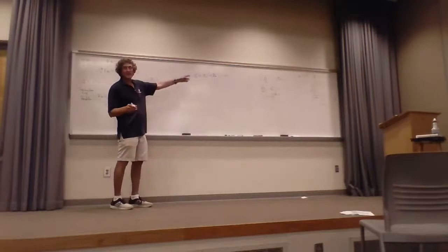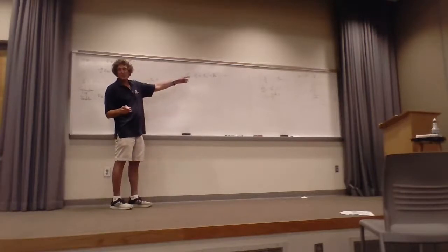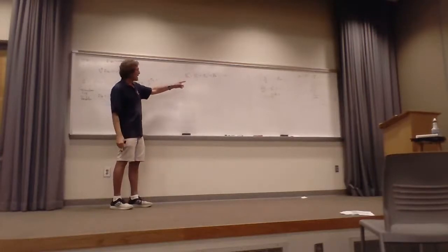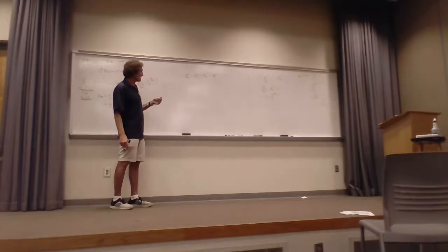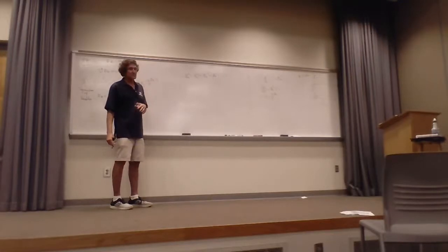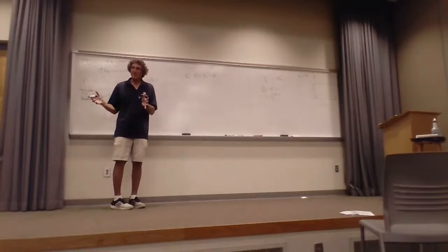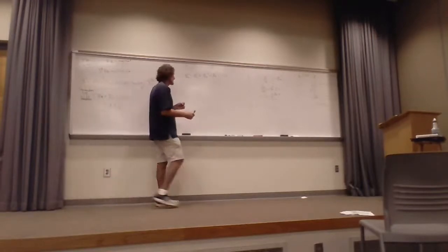Now, I know what beta unguided is. That's omega times the square root of mu epsilon. I know what beta x and beta y are in terms of m pi and n pi over the dimensions a and b. And I know what beta z is, kind of. I don't really. I need to find beta z. Do y'all follow me on this? That's what we do next.